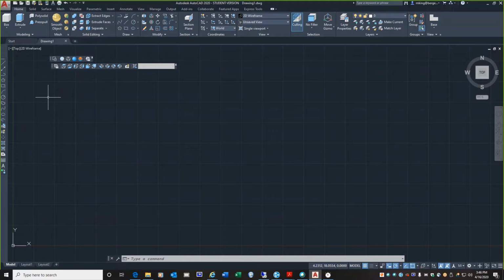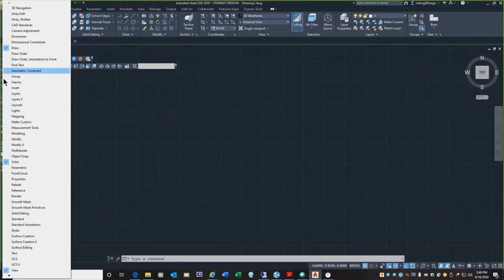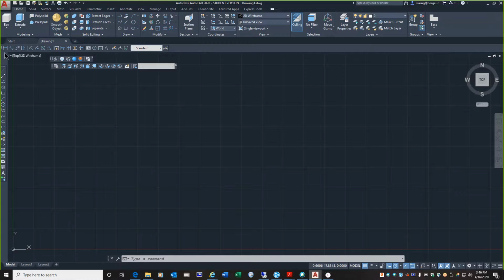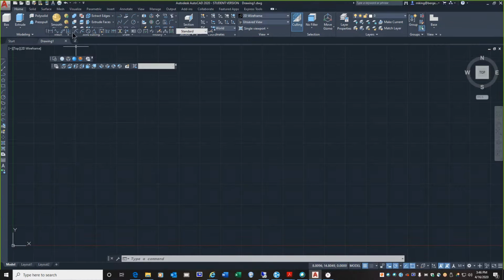And let's put another one on here because this is more or less a helpful tip. Let's add the dimension toolbar in there. So I'm going to right-click and up near the top, dimension. And that's a big one. I think this one goes right into your ribbon. So all of a sudden, you're like, hey, where did it go? It's like camouflaged. But this one goes right in your ribbon area. All right. At any point in the future, if you think, hey, I think I could use one of those other toolbars, all you have to do is right-click on any existing one and grab another one. And I would recommend that you try that because if it saves you clicks, that's what it's all about.